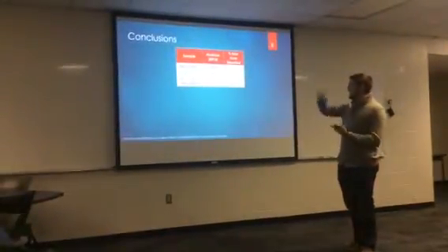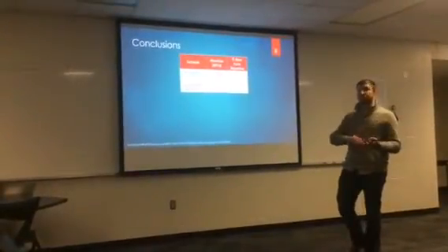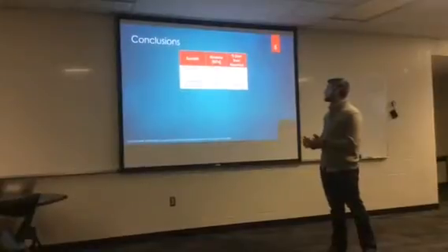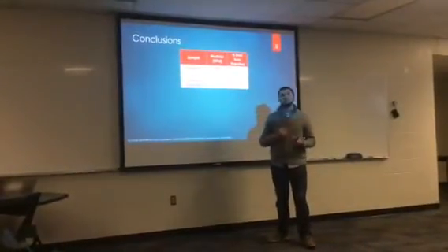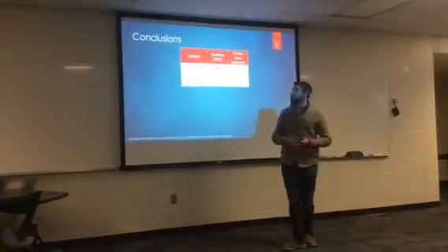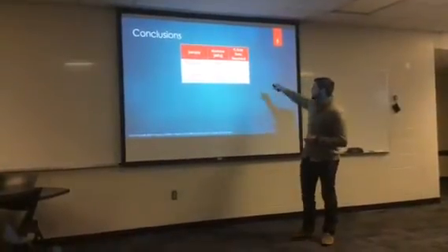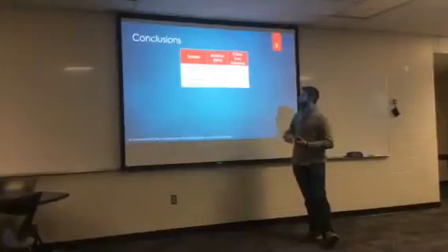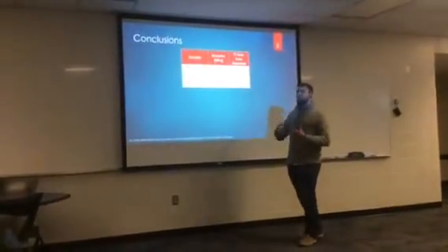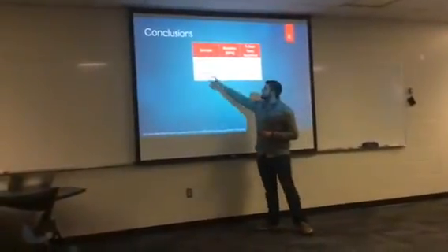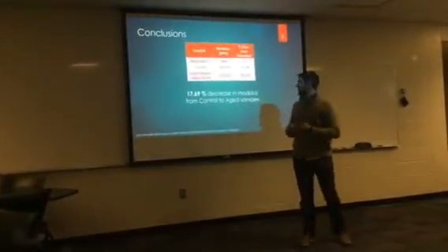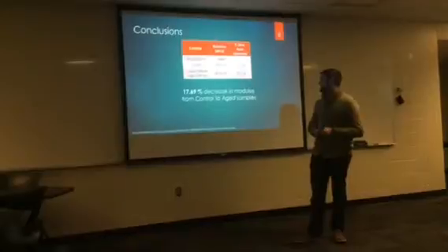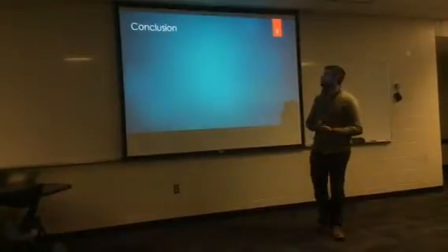So here is a condensed view showing my control samples versus my aged samples. The reported modulus shown here is the number that comes from the material safety data sheet for ULTRALAM. So you can see that my control was only 3% short of the reported modulus. But what I really want to compare is my control samples versus my aged samples. And so you can see there is a decrease in the modulus of 17.69% for the aged samples.